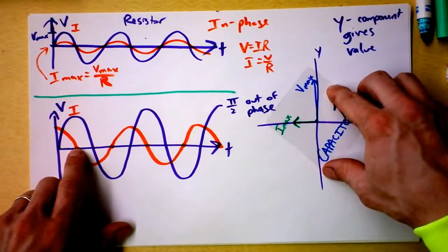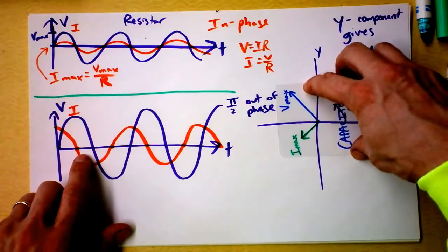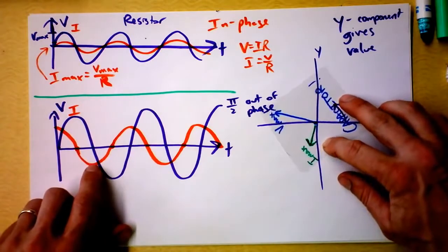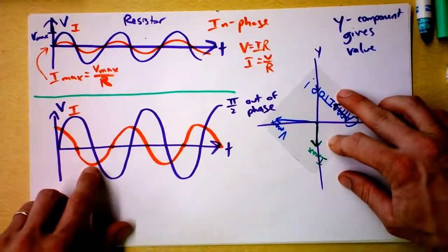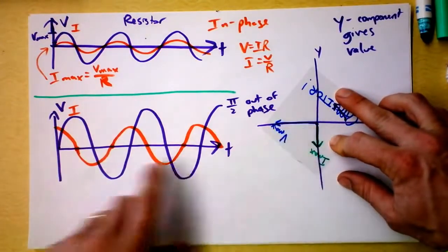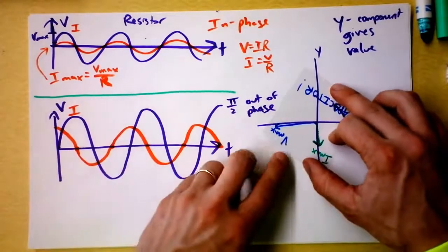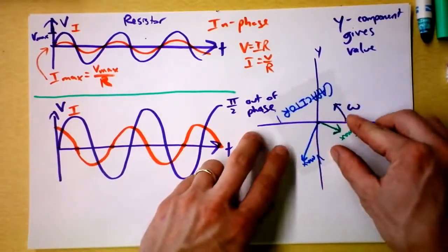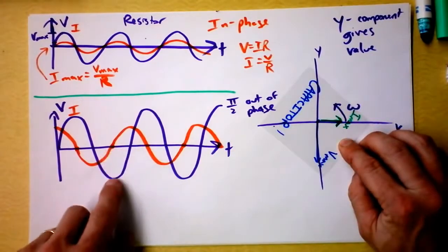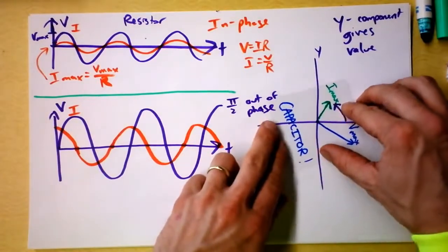And the power supply starts saying, no, let's go the other direction. So the current actually starts unloading, going away from the capacitor and back towards the power supply. And that's here right now. And now we have no voltage. See, the Y component of this phasor right here is at 0, but we have a very negative current. And if we continue going counterclockwise, right here, for instance, we've got no current, but we've got a very, very negative voltage. And as I continue spinning this around, you see how these two things interact.